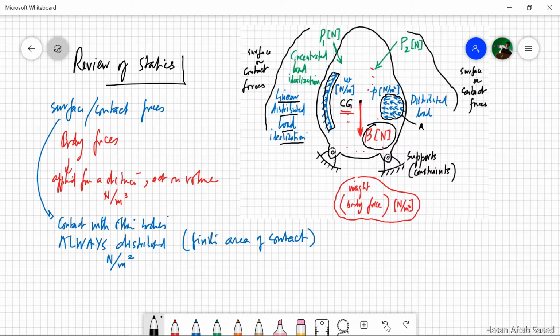The center line is the line shown in blue. In this case, the distribution is then expressed in Newton per meters. The resultant is equal to the area under the loading curve and acts through its centroid.